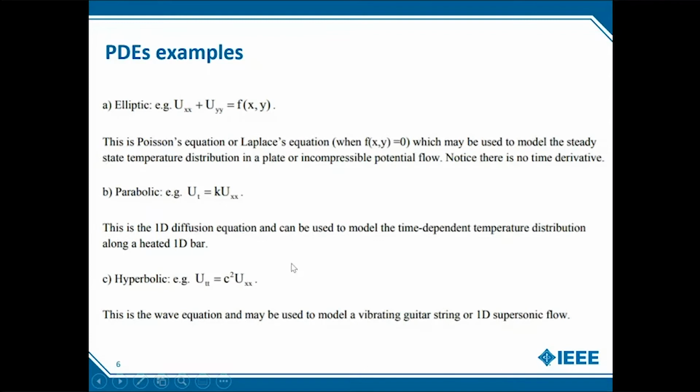And coming to the last class, that is the hyperbolic one, one of the most famous examples is a wave equation. And also basically it can also be a supersonic flow equation. So all those type of equations are governed by this particular template of the partial differential equation. And as I said, these are the most difficult problems in CFD, and there are multiple numerical schemes for these problems, each one of them have their own pros and cons. And before using any of them, one must be sure about the different scenarios that they want to simulate for.